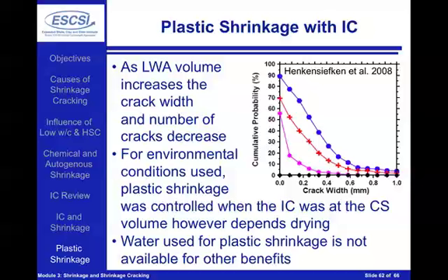And this was shown by Henkensiefken, where we see here the blue being the plain system and increasing amounts of lightweight aggregate being red, pinkish, and the black color, to show that as we increase the amount of internal curing water, we can essentially greatly reduce or prevent plastic shrinkage from occurring.